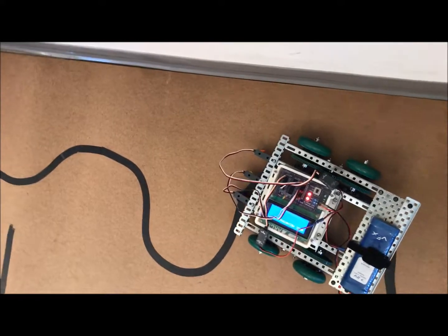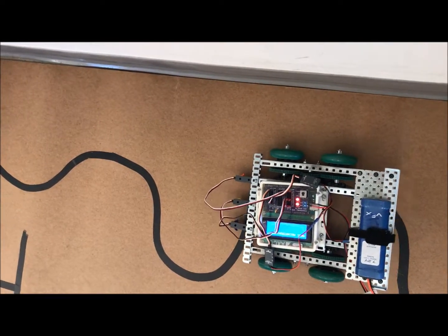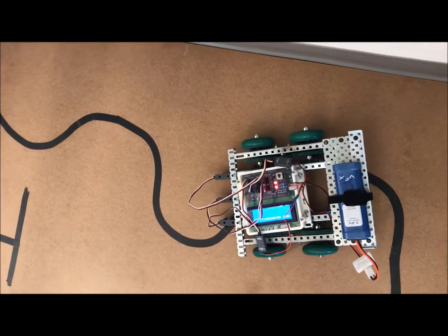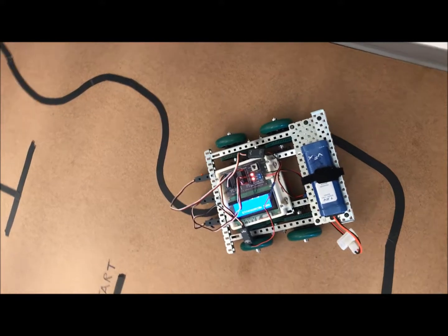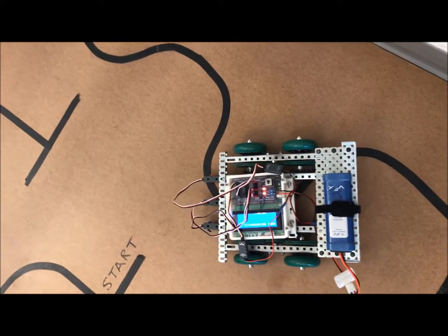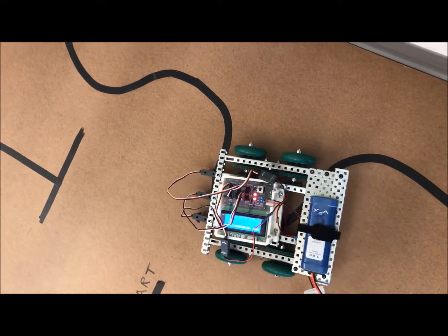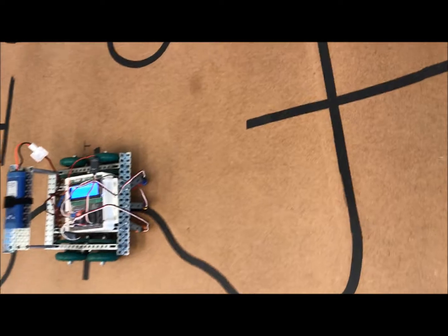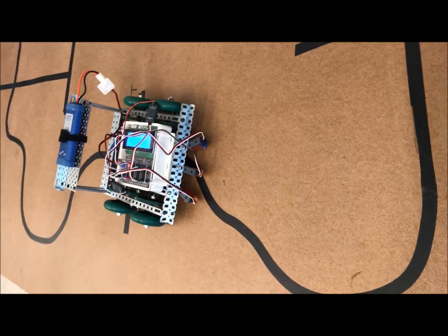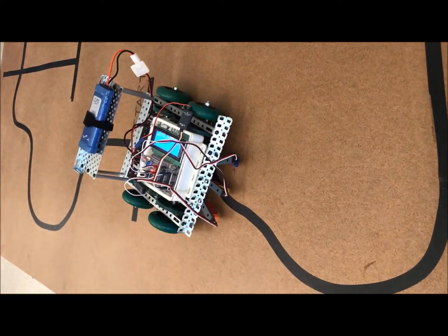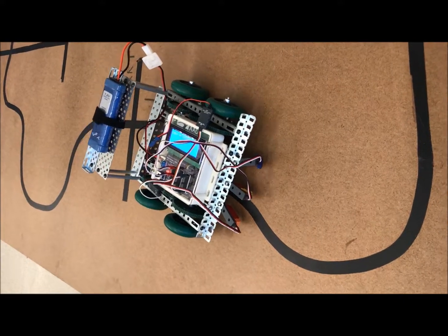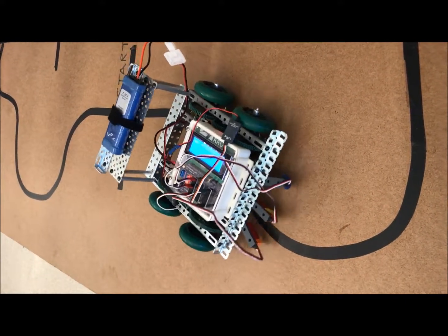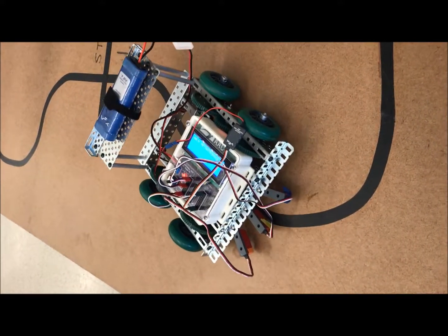For example, I could have made the code so that if the middle line tracker is reading 750 or so, go forward, and if it's not, then it would instead check the left and check the right, and whichever one is higher, then obviously it needs to make a left turn or a right turn or something like that. Possibly a code written that way instead of my code would probably be a lot more accurate.